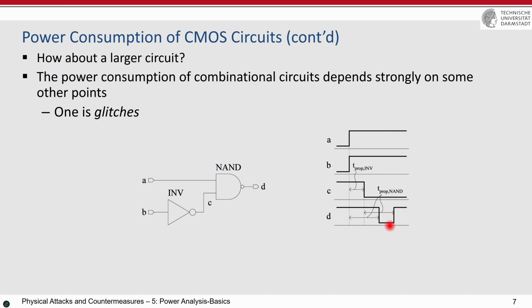And this time depends on what? Depends on the delay of these gates. Because the gates that we have, I mean, we build the circuits with the CMOS gates, they are not atomic gates. They have some delay, in the range of nanosecond, picosecond, femtosecond, depending on technology. And then when the input changes, the output does not change immediately, or the output is not valid immediately.